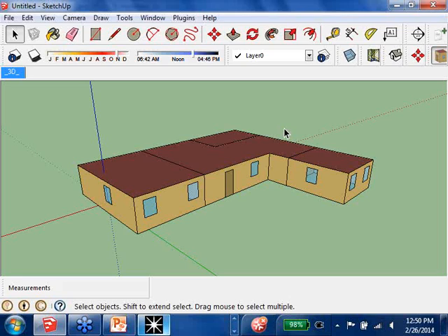So we have material names that are very specific to everything. So we'll have, you know, internal reflectance 50% material or something, and then we'll have BLT 55% material. And then we'll go find those and we'll copy in properties that match those descriptions later on. And I don't know if there's any other options. As far as I know, there's nothing within SketchUp to be able to do that.